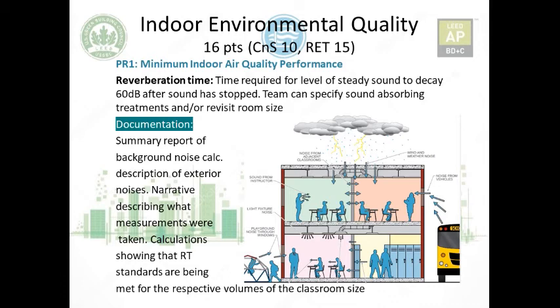Now for the documentation, you have to submit a summary report of the background noise, how you calculated it, what exterior noises you encountered and how you tackled them, and a narrative describing the measures. Then the calculation showing that reverberation time standards are being met for the respective volumes of the classroom size, either greater than 20,000 cubic feet or less than 20,000 cubic feet, and the respective standards are being met.